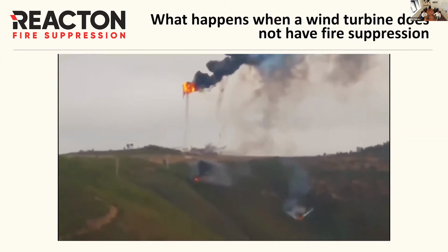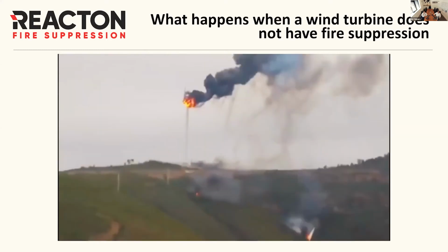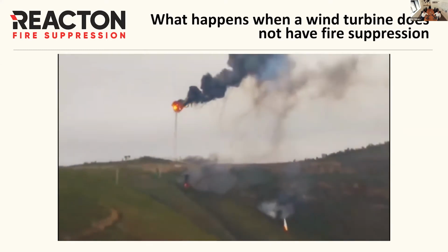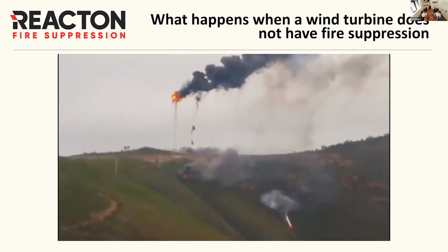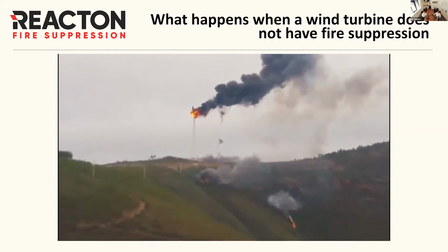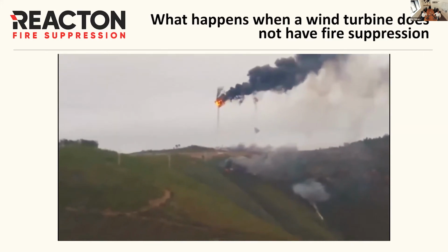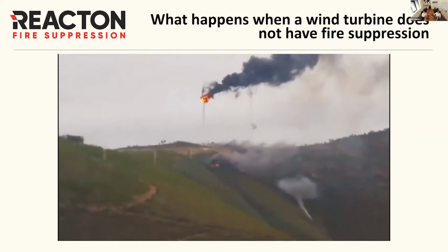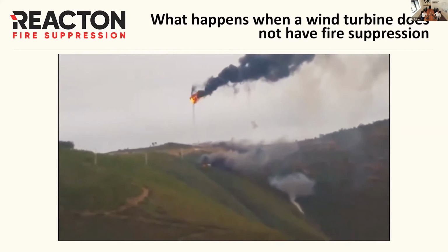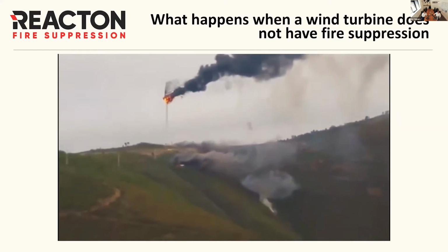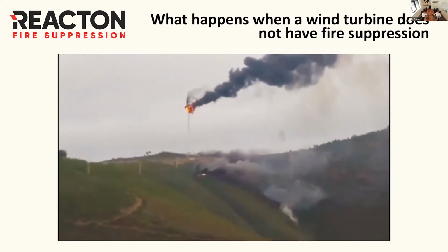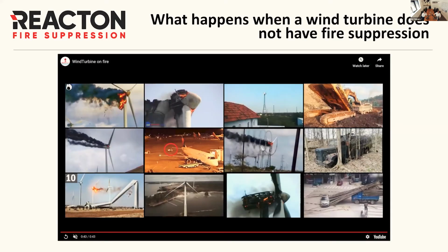It's widely published on the internet about various causes, but traditionally a lot of them tend to stem from brake failure or heat brake fires, where the wind turbine pitch control fails. That's the hydraulic circuit that controls the pitch of the blades, and if that fails and you get a high wind condition, it's down to the job of the brake on the rotor that stops the wind turbine.